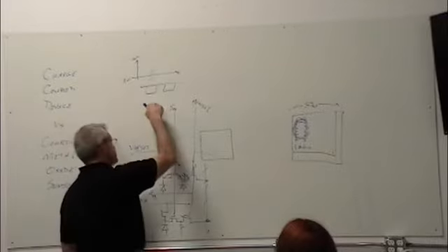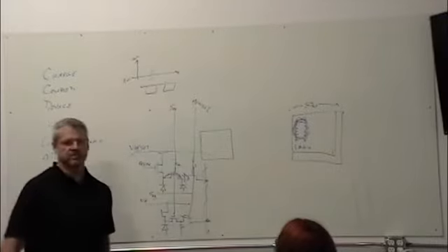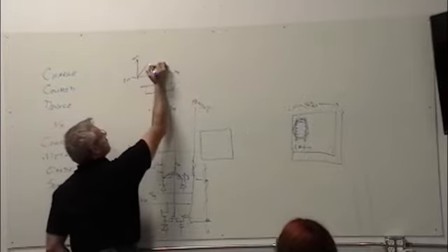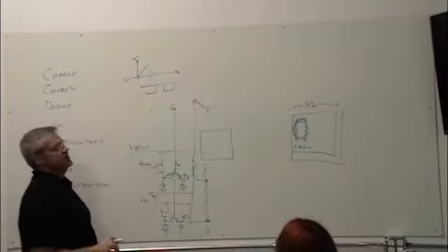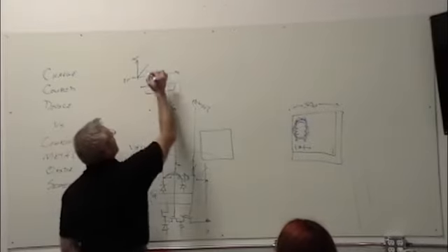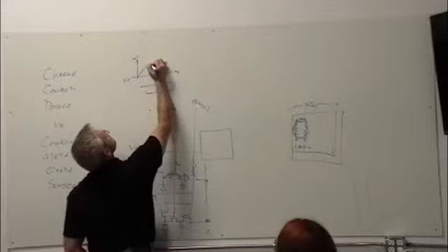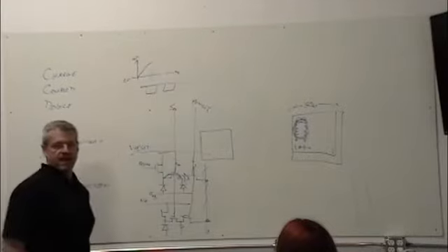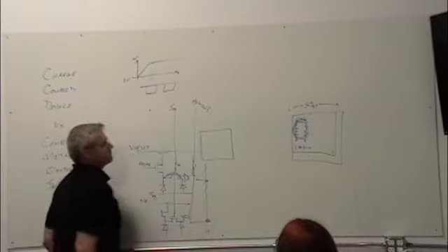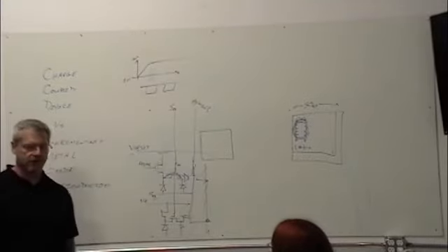A CCD is damned linear, until you get up to about 95% filled, and then it changes slope, and then it flattens off at 100% or around 100%.